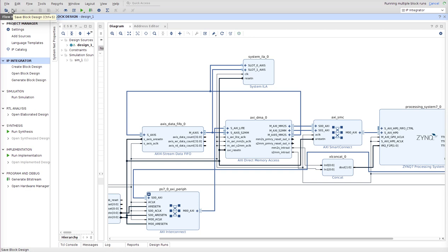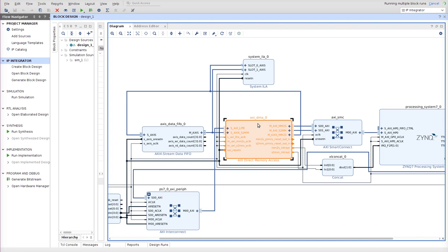Yeah. So just reviewing again, we just added a DMA, and this DMA is in simple mode, so there's no scatter gather. We could have had it with no problem, but I just think that the natural path is to start with the simplest one, which is simple mode, and then scatter gather is still easy to use in standalone mode, but would be a more advanced step.